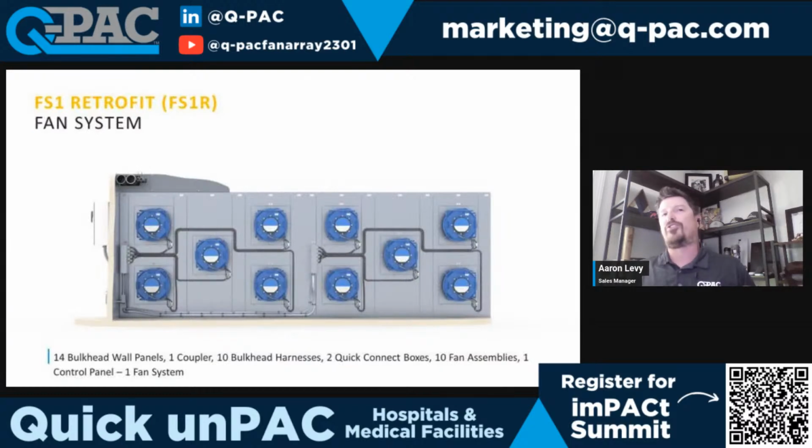And this is just a picture of what the system looks like when it's all together. This is probably about a 50,000 CFM system. I normally figure about 3 to 5,000 CFM per fan. When somebody asks me how many fans would be in a particular system, that's my general rule of thumb. And that really depends on static pressure, but it gets you in the ballpark.